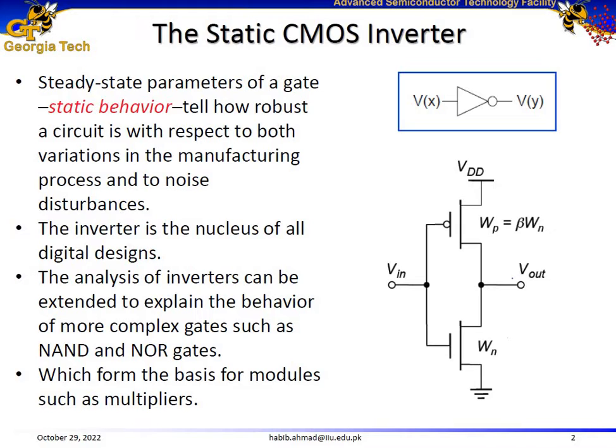For N-type silicon, the mobility is approximately 1500 centimeter square per volt second. For P-type silicon, what is the value? It's approximately 450 centimeter square per volt second. And then the conductivity is directly proportional to mobility. Conductivity is equal to charge times mobility times carrier concentration.